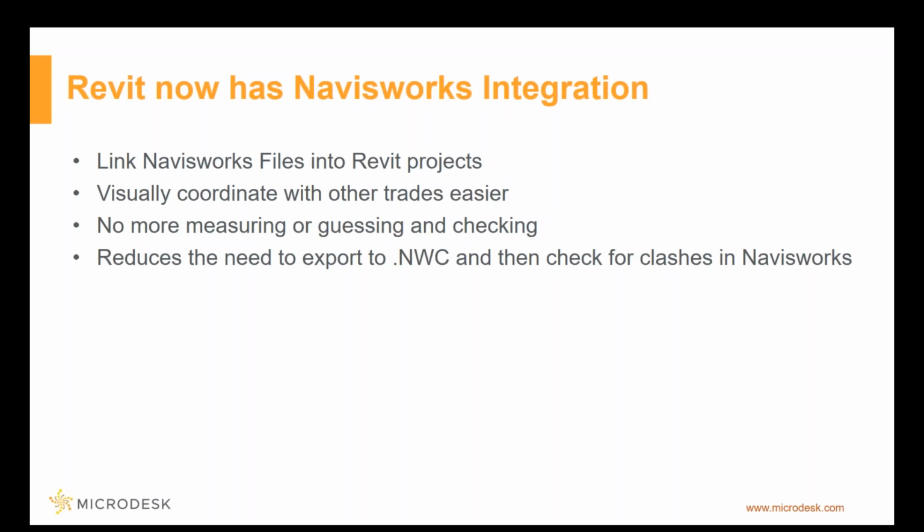It allows you to visually coordinate with other trades. It makes that much easier. You're no longer taking measurements in Navisworks and then moving things in Revit, guessing and checking, exporting the NWCs to see if you've moved far enough. It really speeds up the VDC and construction coordination process, having the ability to bring these NWCs into the Revit native work environment.